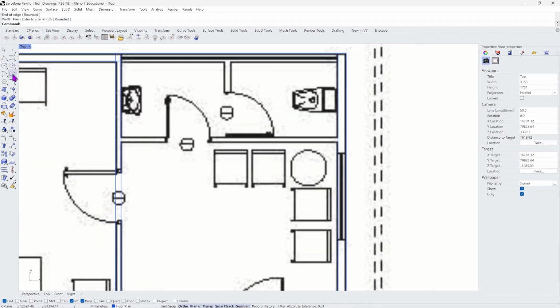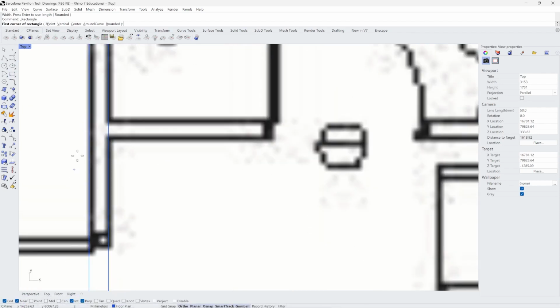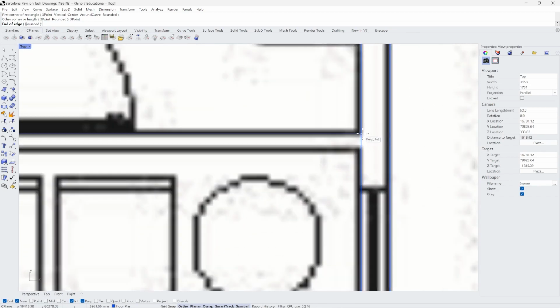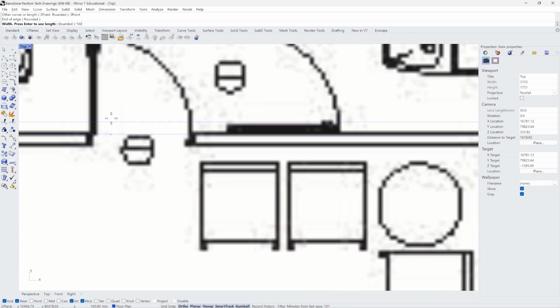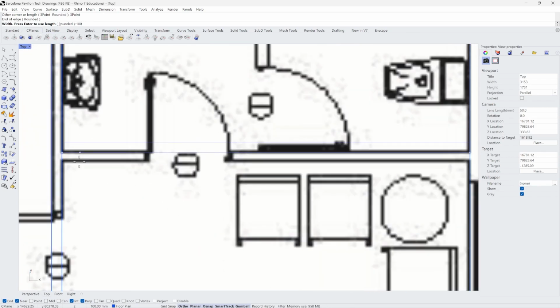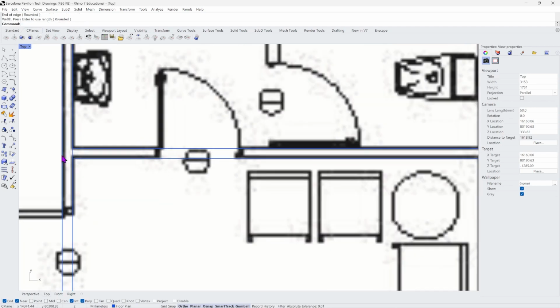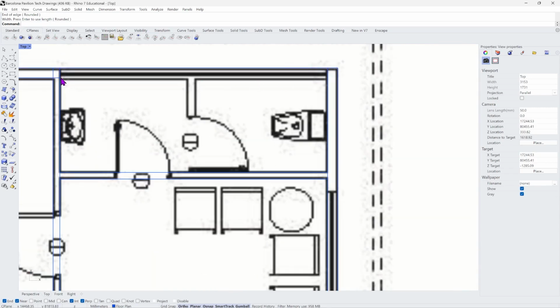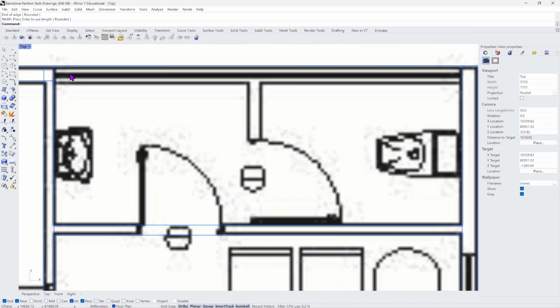We have a couple of more interior walls. So make sure that now you have near on, so we can snap anywhere on this curve. 3 point, go to the other side, interior wall, so the width is going to be 100. If it's stuck and doesn't want to move anywhere inside, you can always try to type -100, or just get closer and move your cursor to the other side, and it should snap to the side that you need it to. It actually also looks like we have a window here, but it doesn't start from the floor, so we have a bit of a wall appearing on the other side.